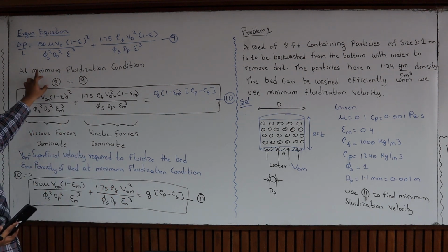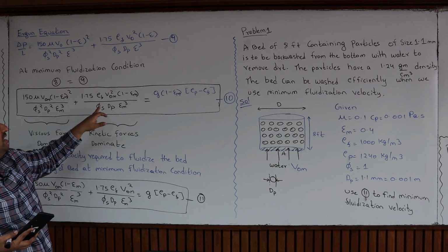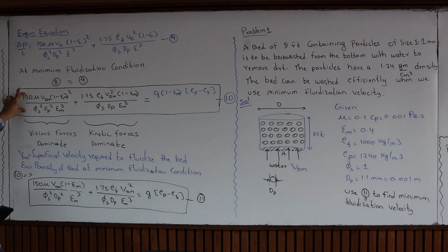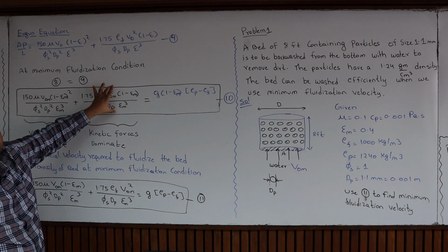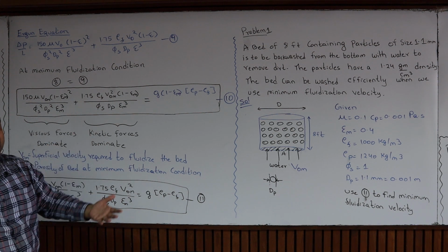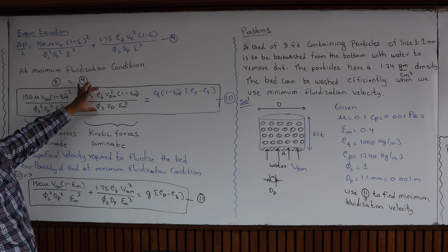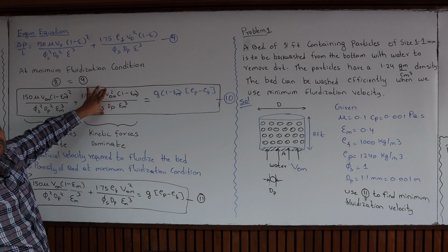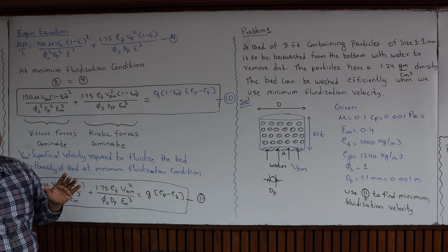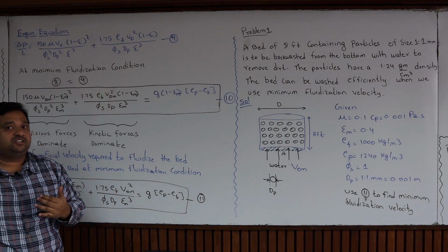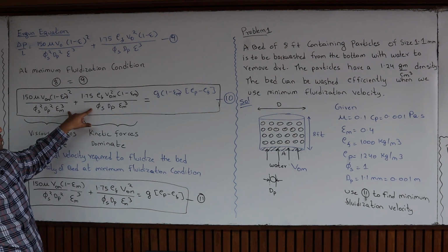So equate these two equations. This term is from the viscous forces. In laminar conditions viscous forces dominate, so you can neglect the other term. In turbulent conditions you can neglect the viscous forces and go for the inertial or kinetic forces that dominate the system. In the intermediate region between laminar and turbulent, you have to consider both terms.